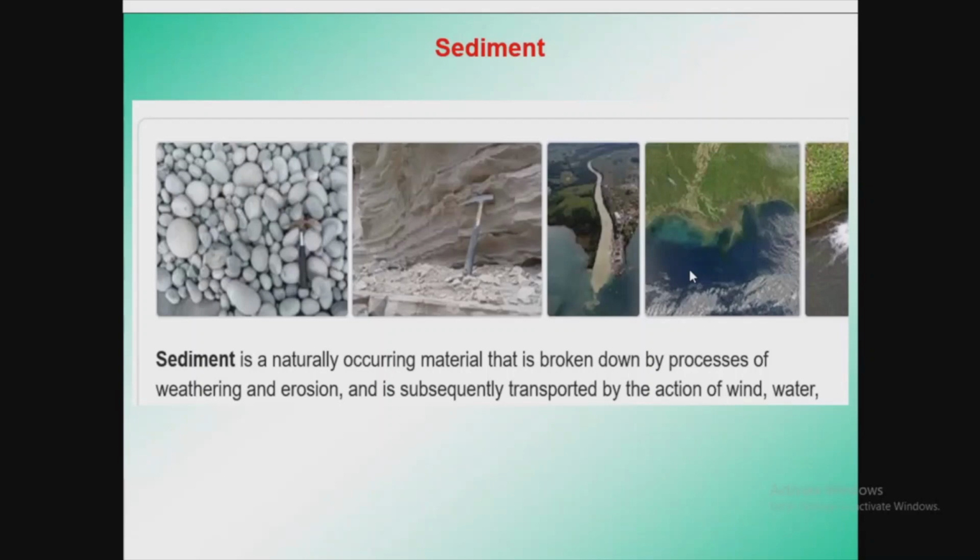So these are particles of earth. These are particles from the mountains. These may be particles from the riverbed, from the river banks, or from the farm fields also. So it may be pebbles, it may be conker, it may be rubble, it may be sand, it may be aggregate. Any type of material which is encroaching on our reservoir area or reservoir capacity is known as sediment.